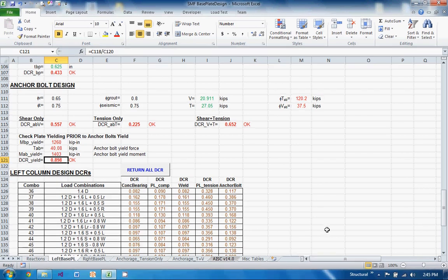So, okay, base plate discussion. That's what that was. All the bolt holes are oversized by 1/16. Your base plate is allowed to be more than that. However, you have to do something to accommodate that if you make it too big.